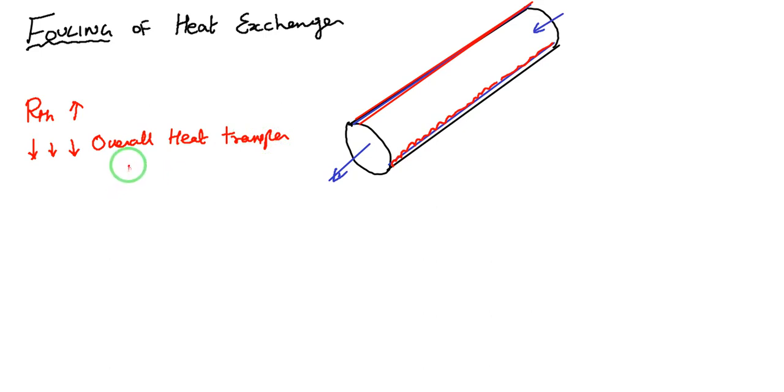Over a period of time the efficiency of the heat exchanger drops. The heat transfer rate drastically decreases because of the rust formation happening in the flow of fluid.